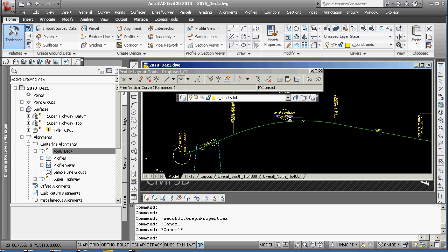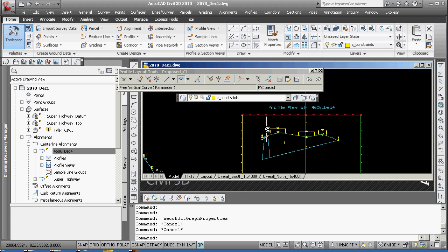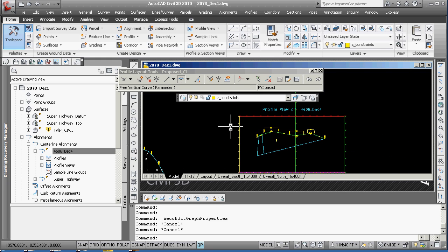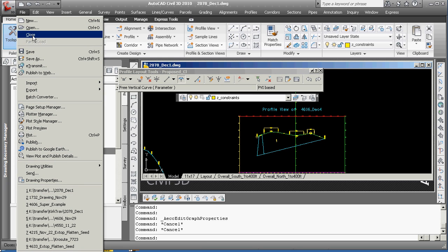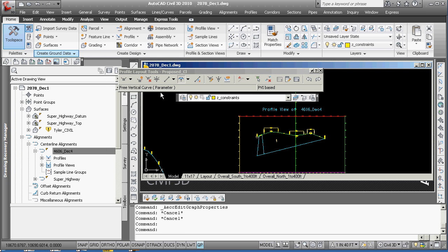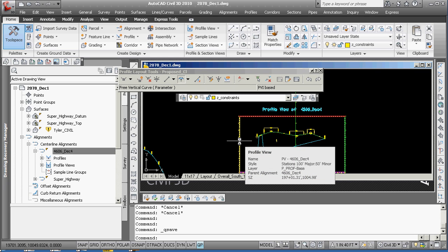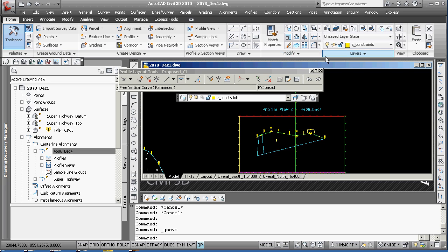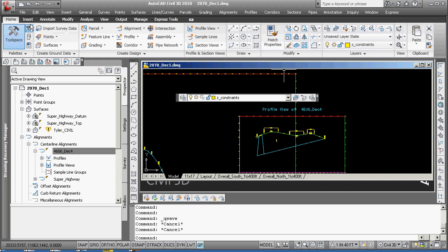You can think about sight distances. You can run out some 3D points. You've got a lot of information here already. So for that purpose, we're going to go ahead and put in some points right away and export them. That's going to be for the visualization coming down. 2 sets of points. You can do this kind of visualization along a path before you actually do the road design. So I'm going to remind you that you can go back to your points.